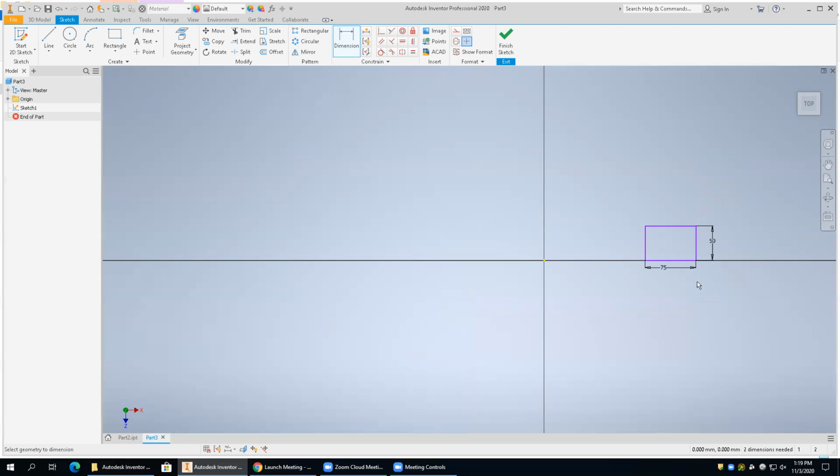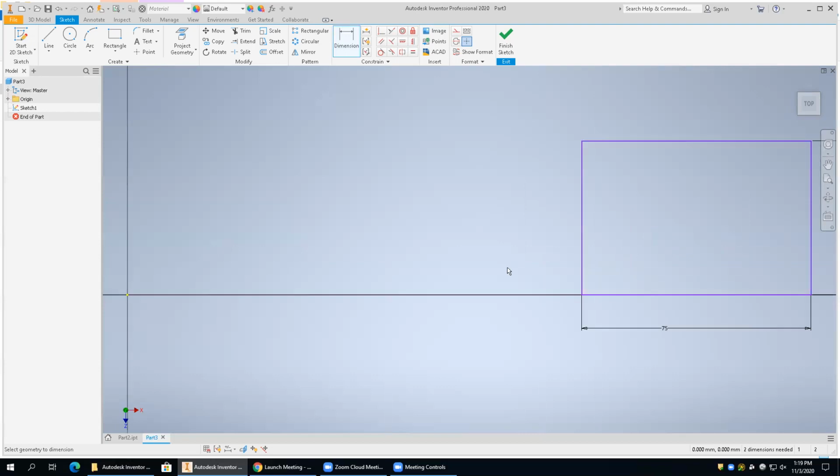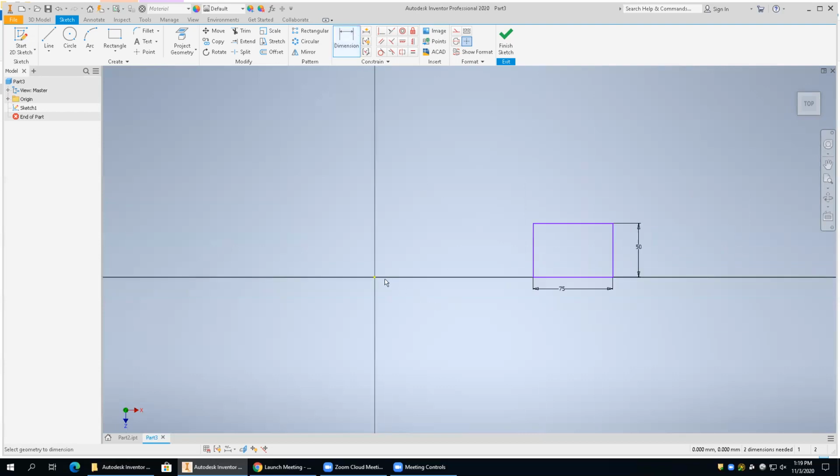We're good? Now, if we wanted to lock this thing down to this corner, because mine moved, I can do that pretty simply. Remember, all I'd have to do is take this dimension and lock that dimension from that point to that point. And whatever that distance is, I could make that 0. It's pretty cool, in those dimensions you can do math. So I could take this dimension divided by 2 plus 20, something like that. But whatever you do here, make sure that you're 75 and 50. Those are the only key things.